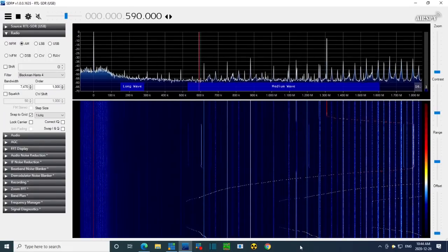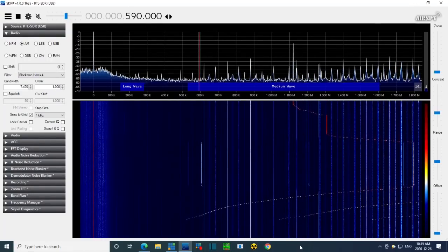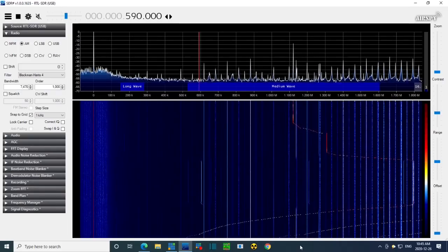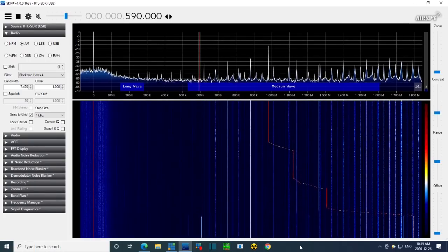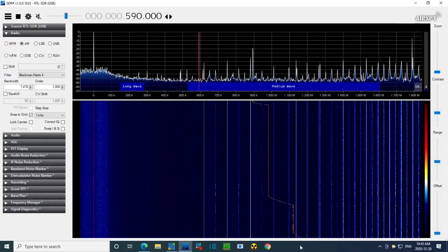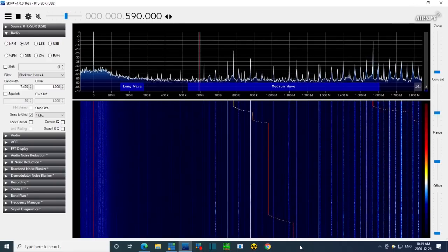Well, that's definitely an oscillator there, as opposed to what I saw last time. And it's a strong oscillator. Okay, so if 175 is the IF and the oscillator runs above, then you'd want this to stop somewhere around here. This would be tuning in 600.